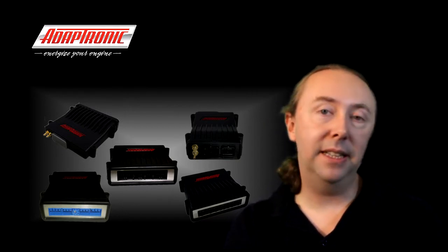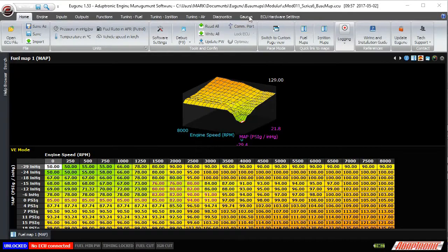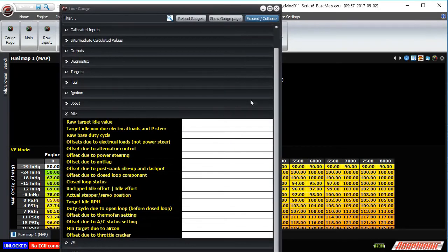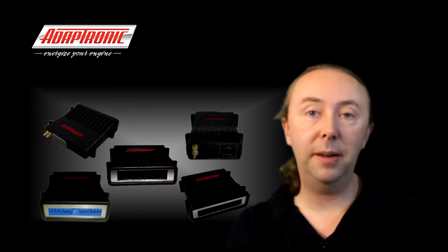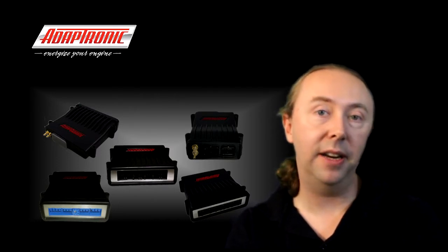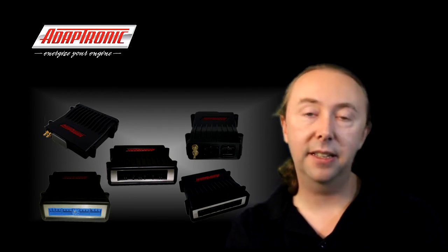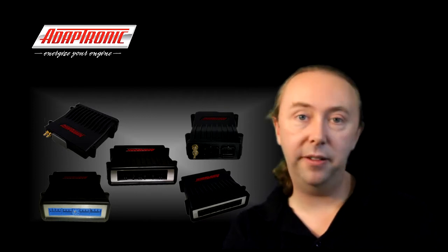Firstly, let's find where we can see the idle effort in the software. You can see it on the gauges window next to the RPM. The RPM field shows the current RPM, the target RPM and the idle effort, which could be a duty cycle or a percentage of the number of steps or a percentage of the maximum throttle authority on an electronic throttle engine. But it's expressed as a percentage so that it's consistent between all those variations. And of course you can add it to a monitor window if you want to.